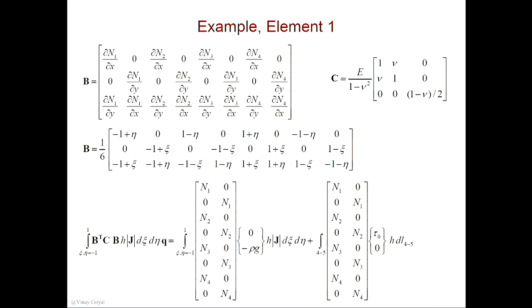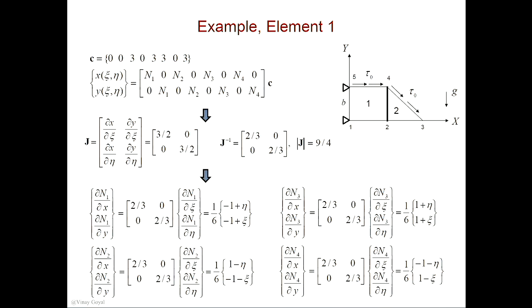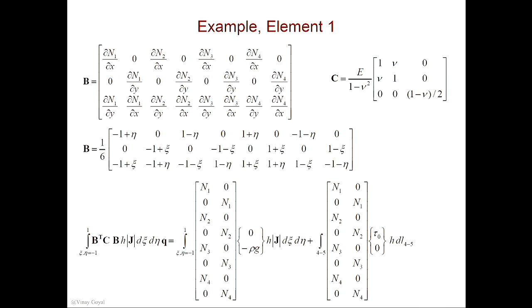I'm going to ignore this a little bit longer, but we can cover it a little bit now. So if you remember, I'm applying a surface traction, and I'm applying surface traction on edge 4, 5. You agree on element 2, 1? Yeah? So that's a surface integral that I had to calculate. If you remember, that was N transpose times traction, bold. So traction bold, you saw that in the previous picture, T bold only had components along the x direction. So that makes sense, tau 0. There's nothing going downwards. So traction in the y direction is 0.